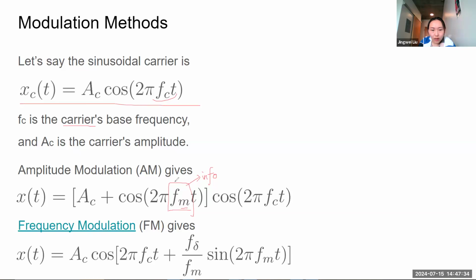This is the time varying signal that we generate, and this signal is added to the frequency, although no, added to the amplitude. AC is the amplitude. So your amplitude will add this modulation. This modulation signal is added to your amplitude, and then this sum is multiplied by the carrier wave. This is why it's called amplitude modulation, because it modulates the amplitude.